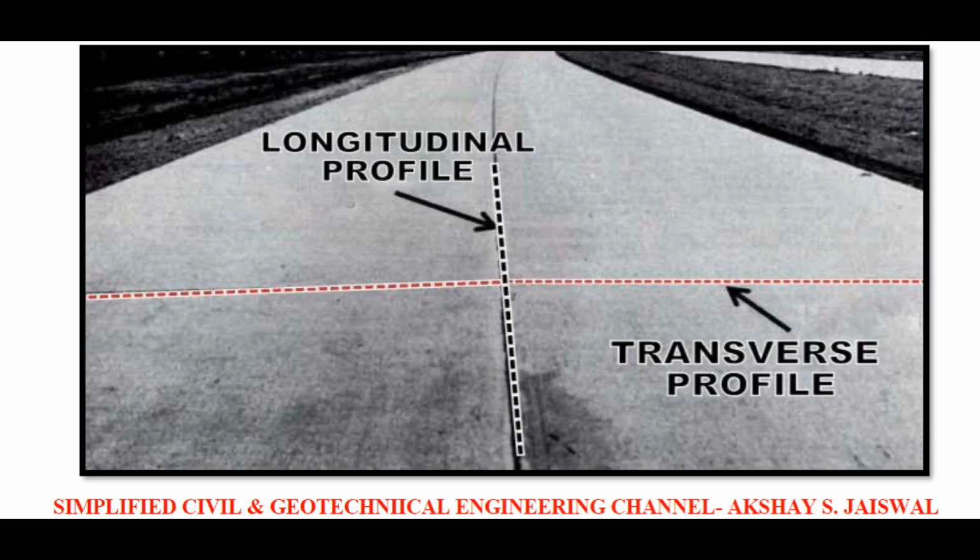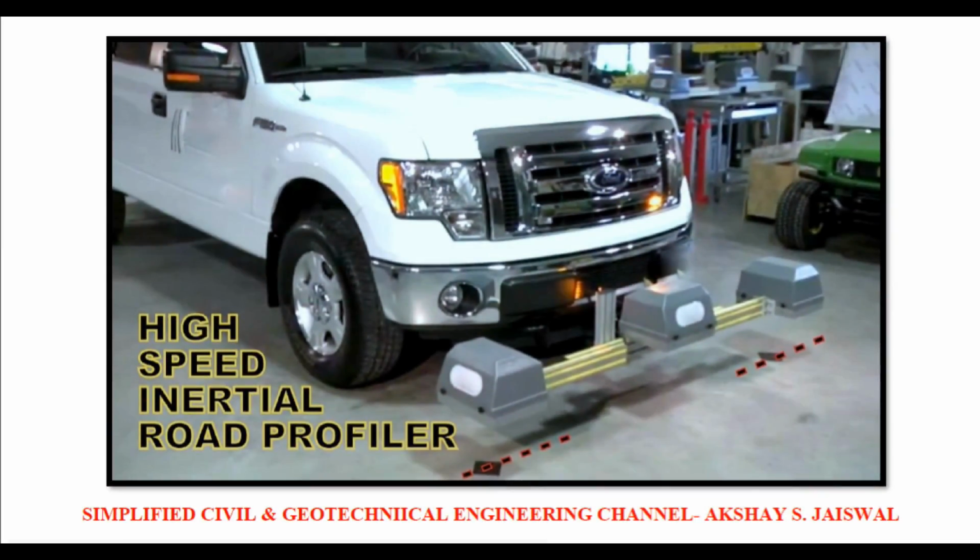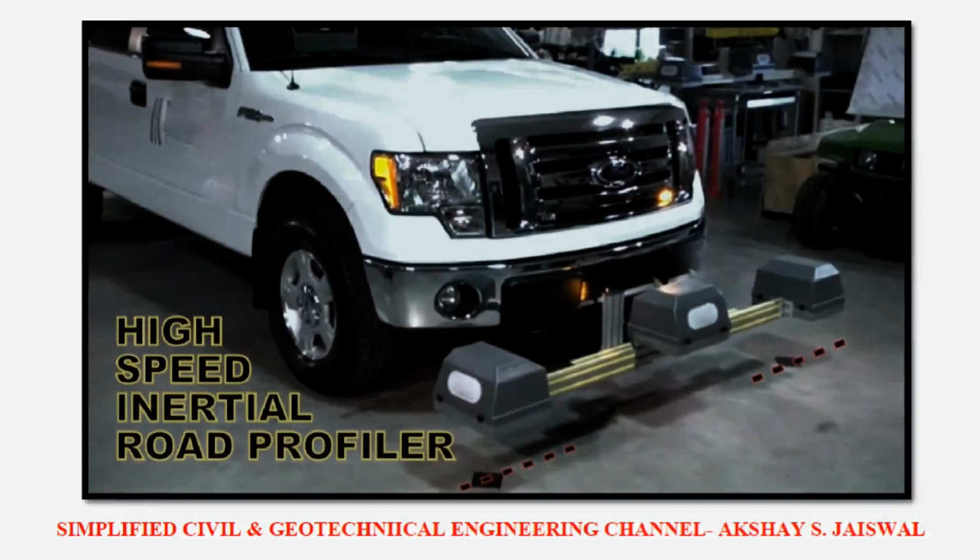The International Roughness Index is a mathematical property of a two-dimensional road profile. It can be calculated from profiles obtained by measurement methods such as level surveying equipment to high-speed inertial profiling system.